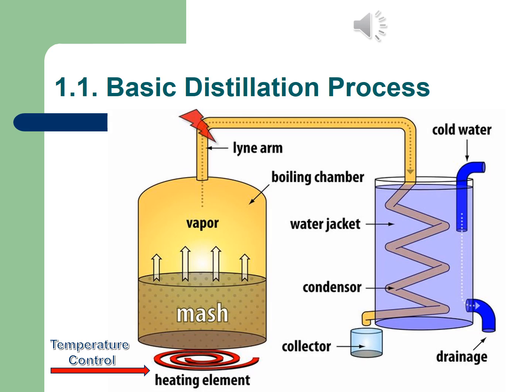Then after a while you can move up to a higher temperature, you can get your ethanol from this, by cooling it down in that heat exchanger. And then also called then a condenser. And that will all be collected then in the collector. If you go to a higher temperature, then you will start to actually also get water part of this. So again, it's very important to closely then control your temperature.